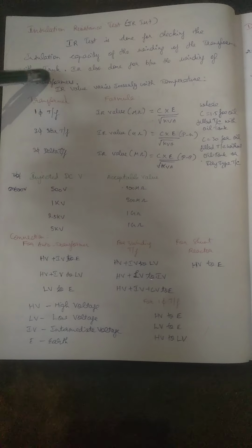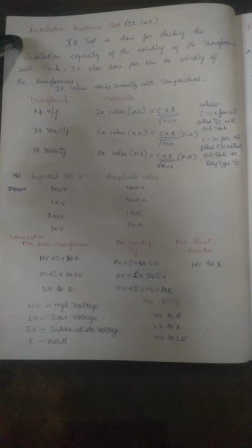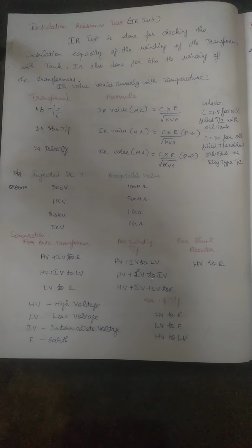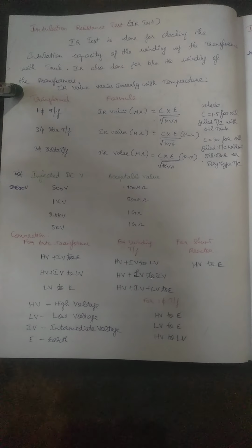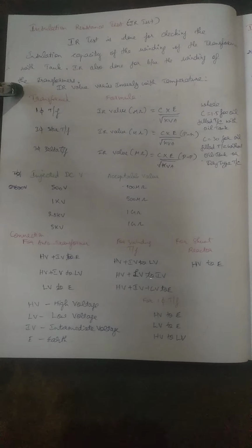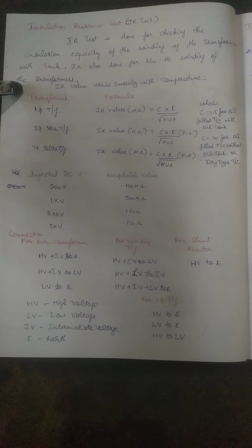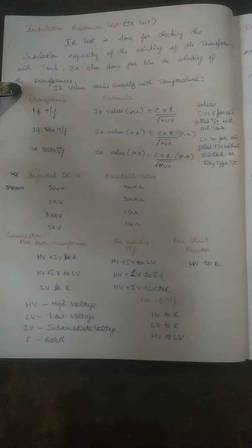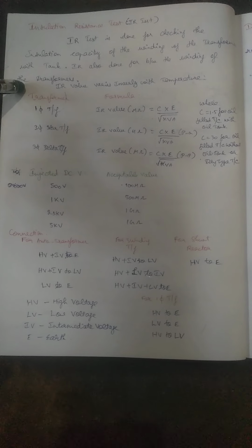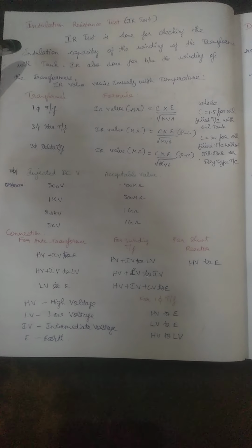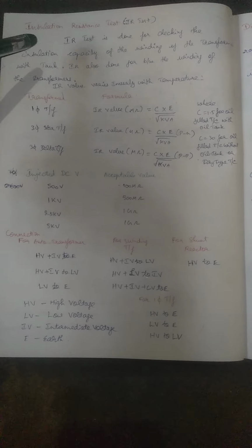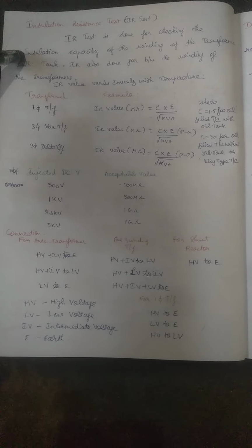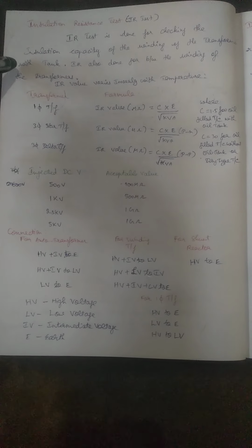The insulation resistance test is used to check the insulation capacity of the winding of a transformer, which means the space between the winding of our transformer and the tank, which is connected to the ground. So the insulating capacity of our winding and tank should be cleared by an insulation resistance test, because if